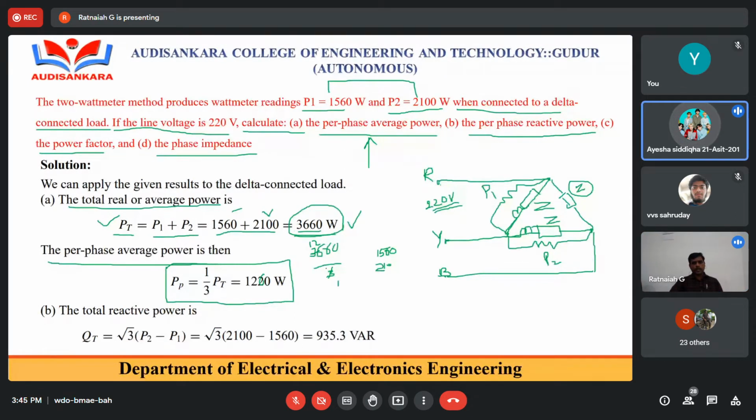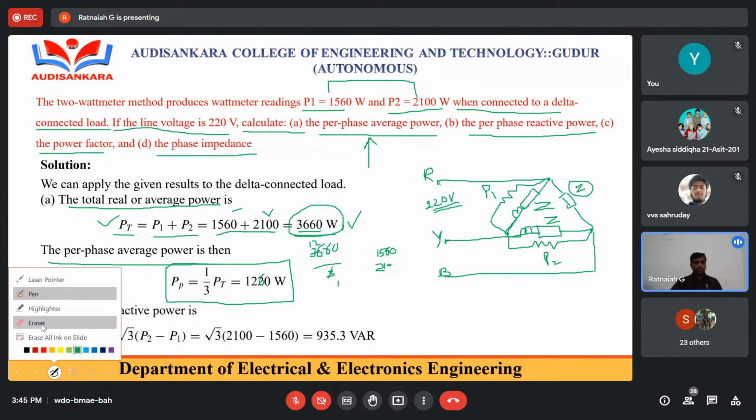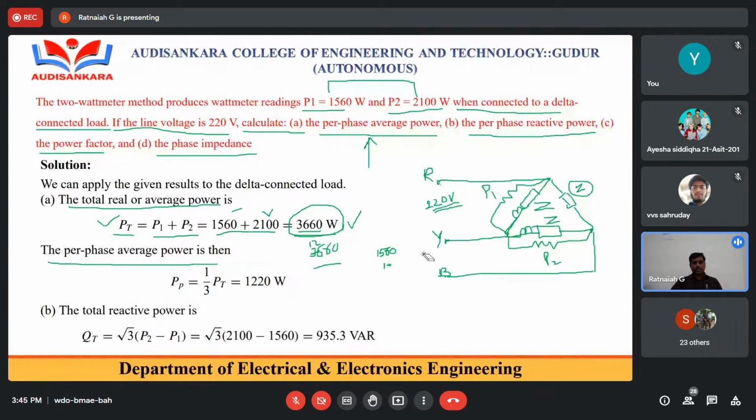Correct, sir. 1220, right. Sorry, I'm thinking about the first digit only. So this is 1220 watts, right? So the per phase power is always 1220 watts. That is, divide the total power by 3, and there you can get the per phase power. That means the impedance or the load absorbs a per phase power of 1220 watts.